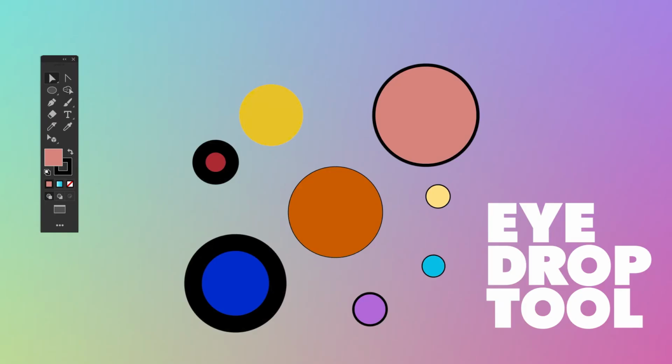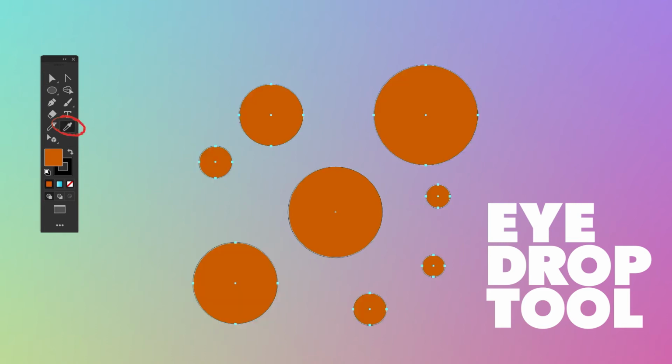Okay, so now you need to copy one style of an object to the next. That's when you're going to use the eyedrop tool. Let's say that I want all of these objects to be orange. I will click on the shapes, go to my eyedropper, and then just eyedrop on the orange.